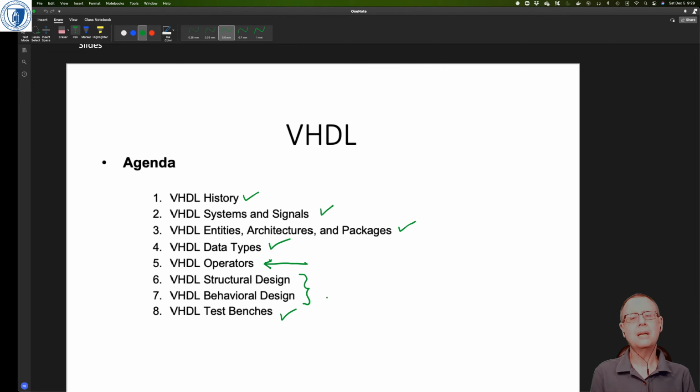The only slight thing that almost convinced me to switch to Verilog is that there seemed to be some more modern open source tools available for Verilog. But for what we need to do in this course, Quartus and ModelSim do everything we need, and they're both available freely. So I thought we'd just stick with VHDL.